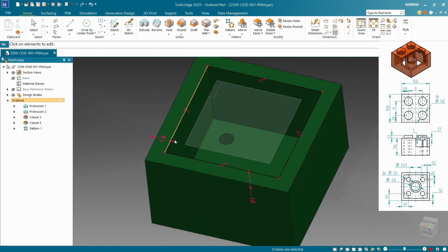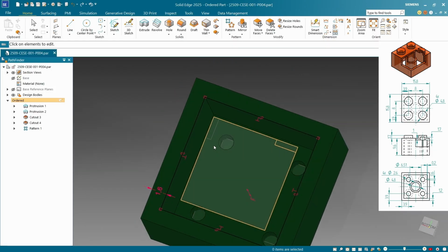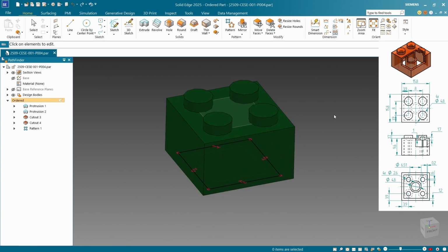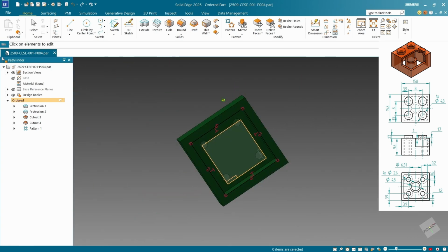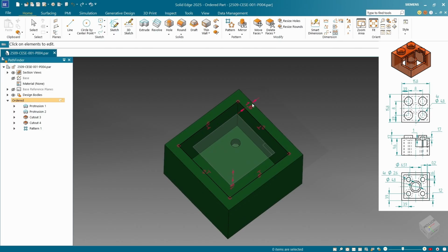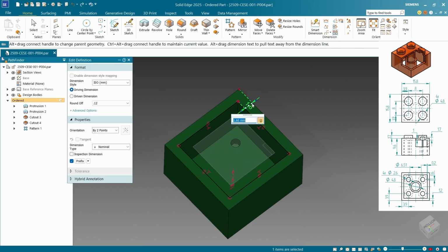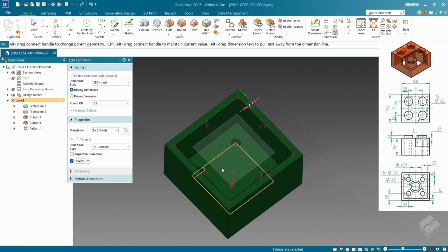And it's basically a 1.6 millimeter dimension here. And you can see another 1.6 millimeter dimension offsetting it from the top face. So let me just click on that 1.6 millimeter dimension, change it to 1.2, hit enter. That changes all 4 faces around there.